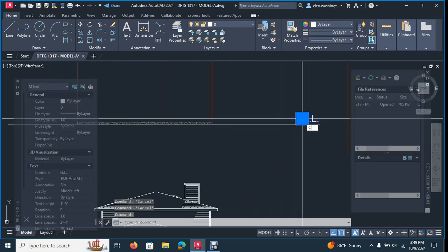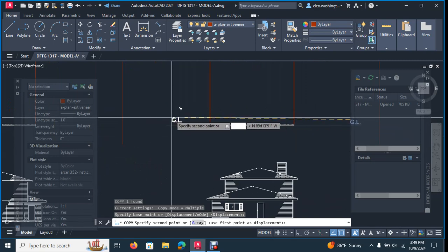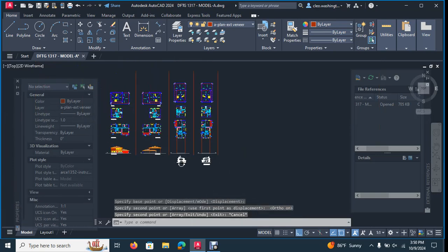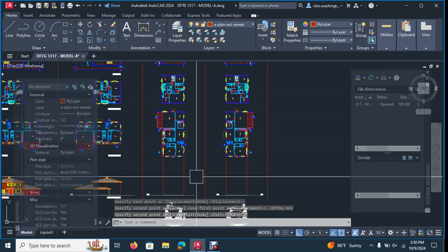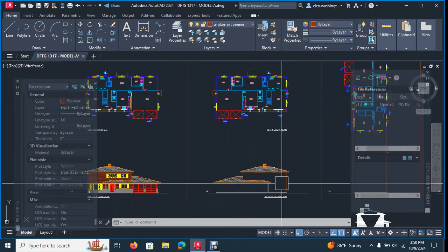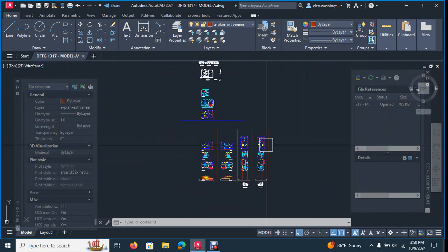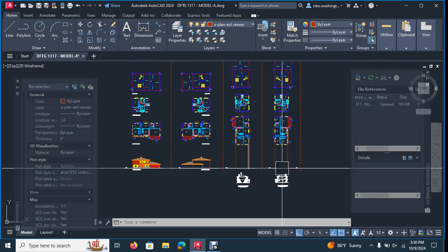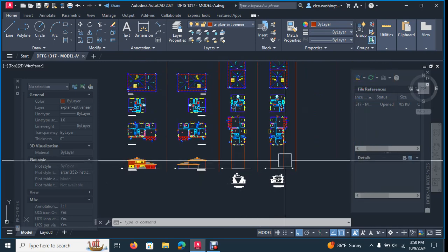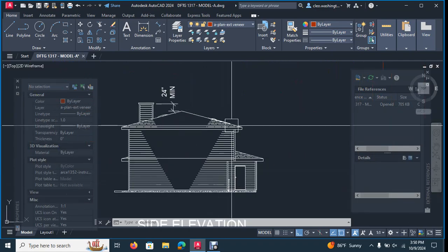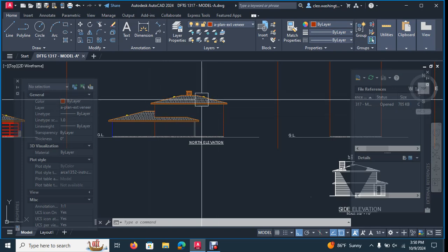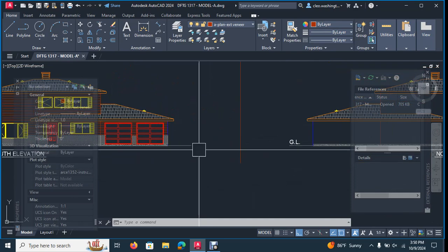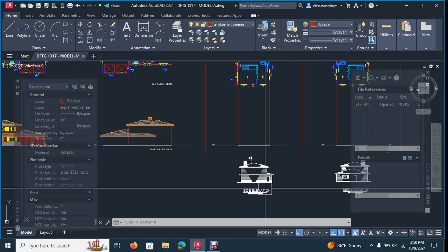As you can see, these guys, they don't have as much to them. They're very simple. And I've shown you how to project the lines down. You project the lines down from the first and second floor on the roof, and then you get this guy, right? So good. That's what I want you guys to do next, is to actually go ahead and finish this elevation, add in your windows and doors, and go ahead and produce the final two elevations, which are very, very simple. This is all you'll be producing, except it's going to be set to these layers and these standards and these finishes, okay? I want you to carry the brick and all the stuff over with the hatch pattern like I showed you.